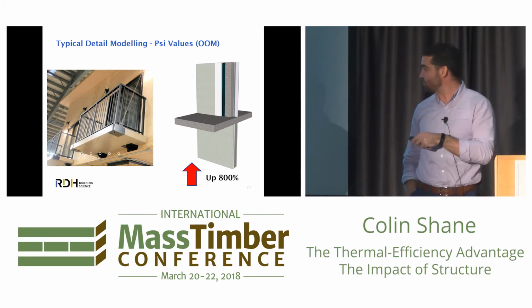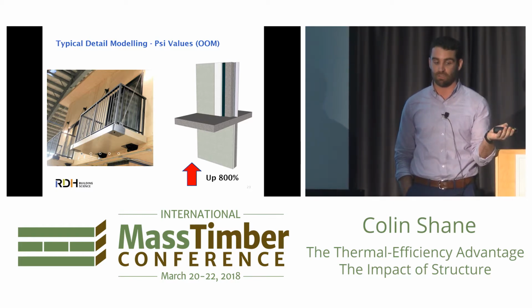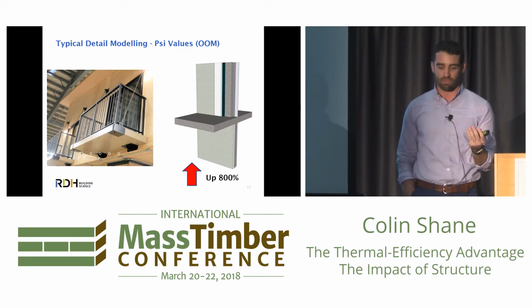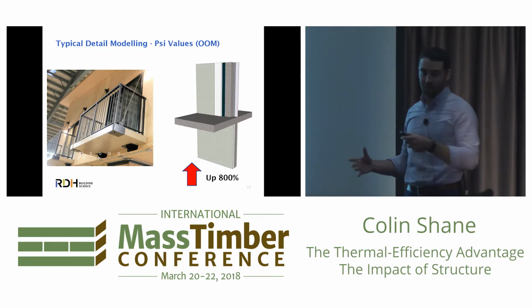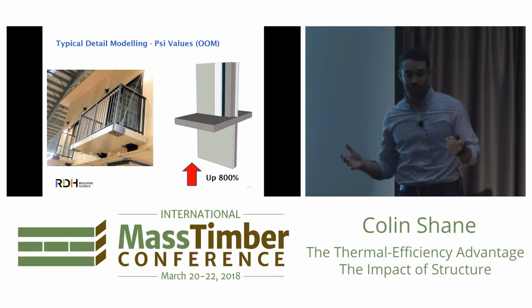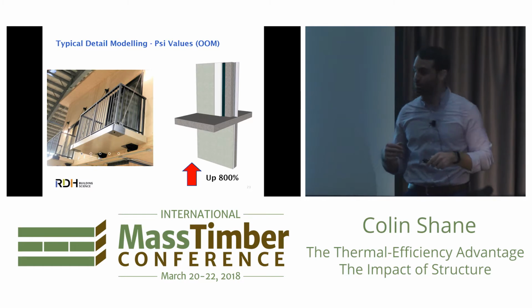Right? So the difference of using mass timber products or other types of products that are more insulative at these interface details, we can drastically reduce the linear transmittance across these interface details. And again, very often these are things we just overlook in energy models and forget about. So even if our energy model says that these two buildings are the same, the reality in real life is a whole bunch of these details that we've overlooked in preparation of our energy models, actually we save a lot of energy by doing that in timber.